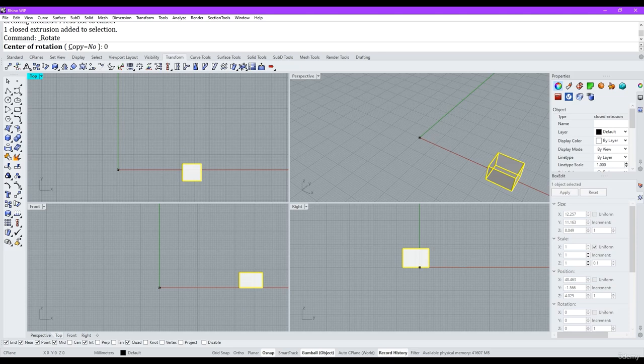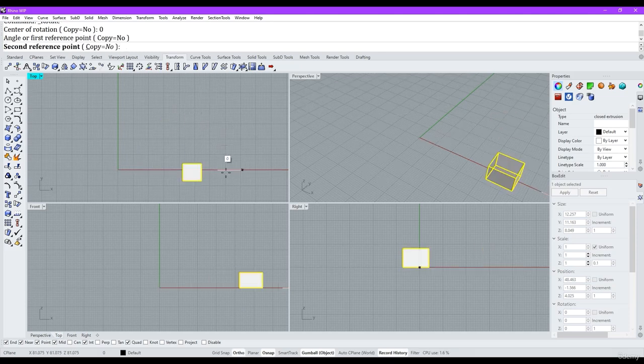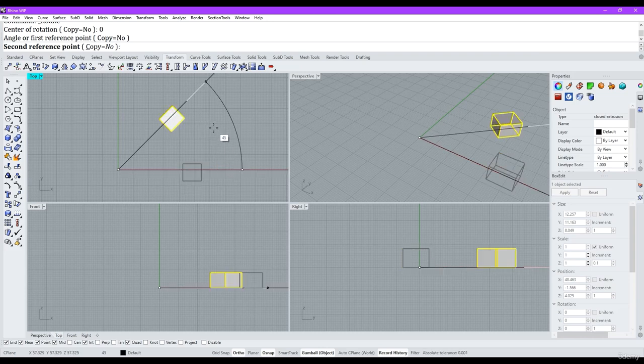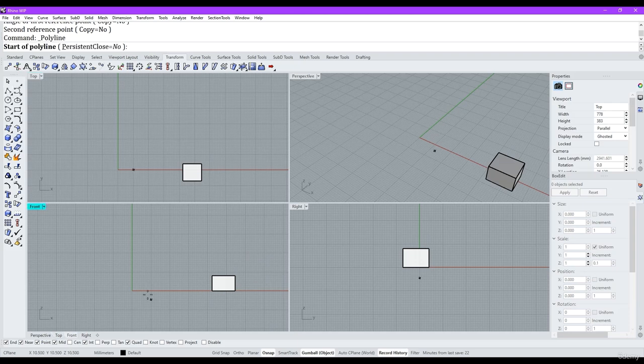I can rotate from world origin, 0 and enter, hold down shift, and now I can snap to 45 degrees. Now, with that cursor tooltip, when I draw a line, for example, it will show the length of that line in that little box next to the end of the line. That's what those 2 options do.